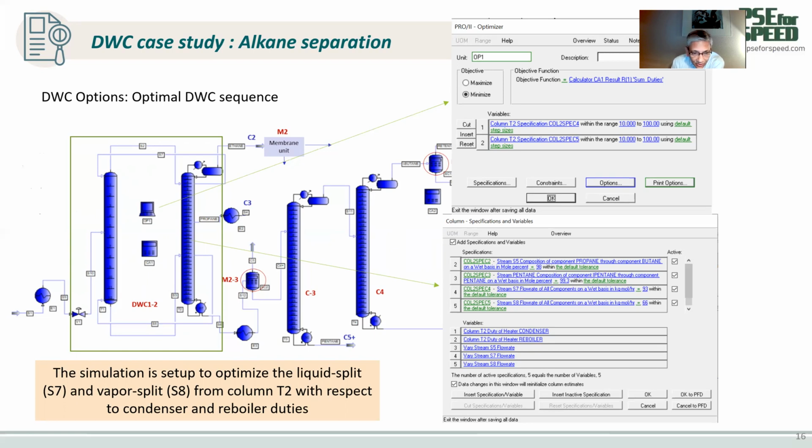So this module, we can add in any process flow sheet where we want to replace 2 columns with 1. So that's one way. So we can always add things before it and always add things after it. It's not very easy to converge because the iterations for the optimization of those 2-tier streams can take a lot of time. But if we start with that, the first column always has enough liquid and vapor, then it will never break down. And if it does not break down, ultimately column 2 will converge. So it's not a problem.